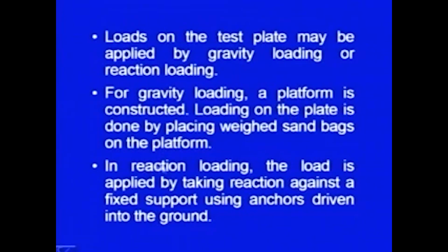In the second case, in case of reaction loading, there is no platform, in fact a frame is there, and load is applied by taking reaction against a fixed support using anchors. So, there we use the anchors. These anchors are driven into the ground, and from those anchors and using a frame, then we take the reaction.